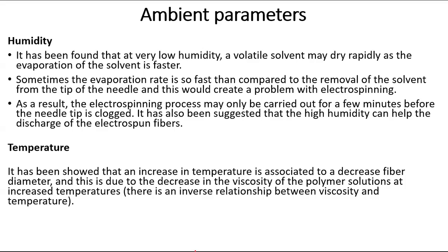So therefore there could be certain repercussions. The electrospinning process may only be carried out for a few minutes before the needle tip is clogged. It is because at the tip it is a very fine tip. It can get clogged if the evaporation rate is too fast.